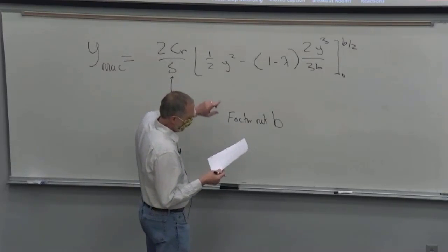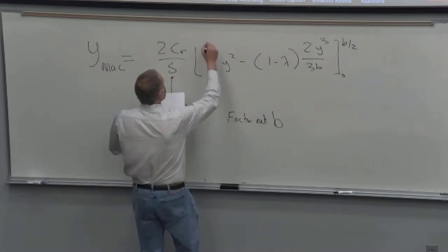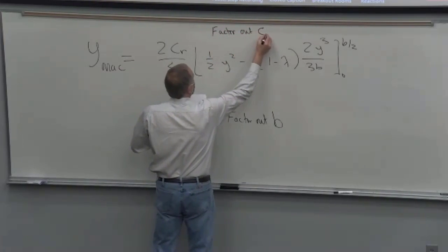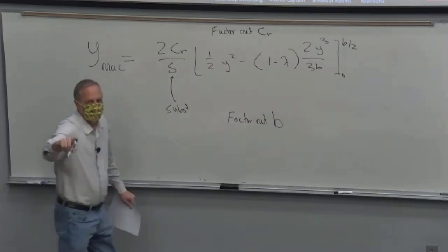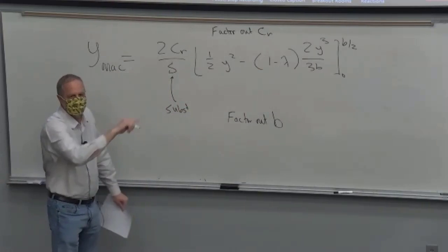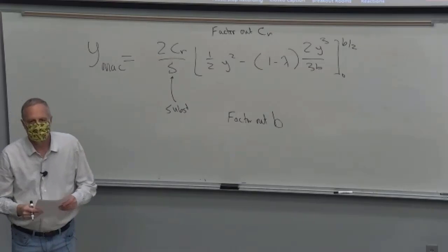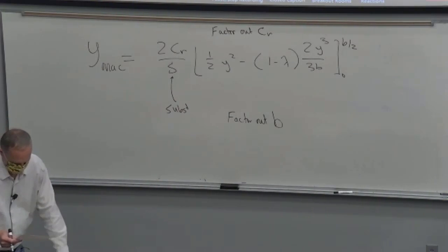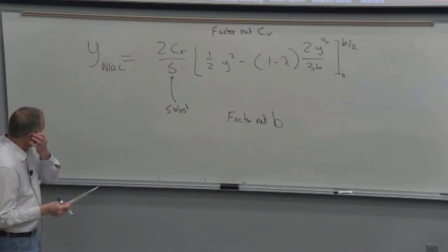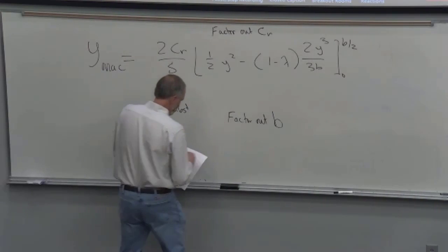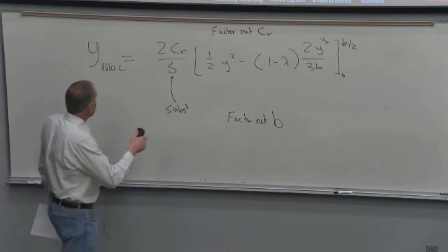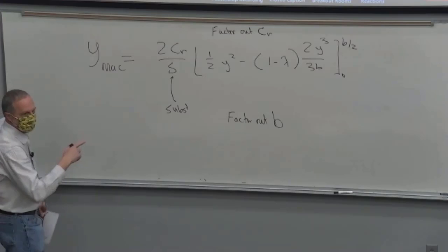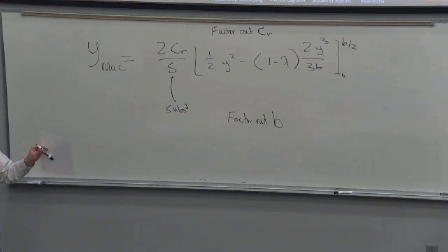So let's see, I guess somewhere before here, you have to factor out the root chord. You'll get an expression, you'll factor it out, and that's what gives you the ratios of the CTs over CRs. Well, I'm going to show you a shortcut for XMAC. Takes the whole page if you just brute force it.